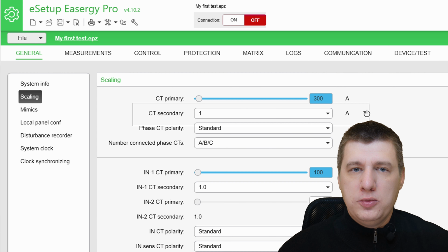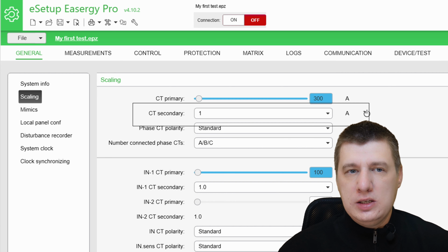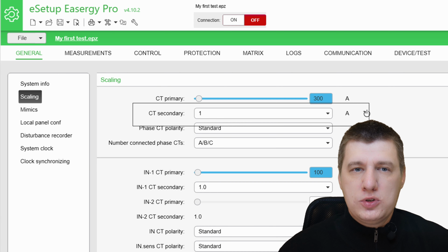The relay analog inputs are designed to impose minimal burden load on the CT secondary circuit to maintain measurement accuracy. Conventional phase CT inputs have an impedance of less than 0.02 ohms. The secondary inputs can handle a continuous current of 20 amps and a 1 second surge of 500 amps.